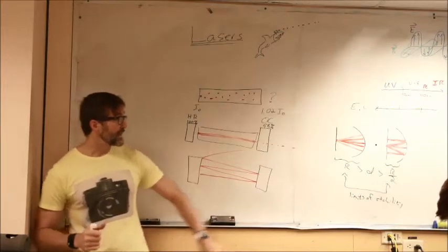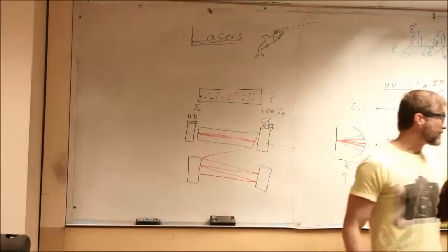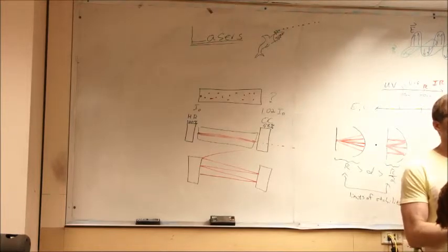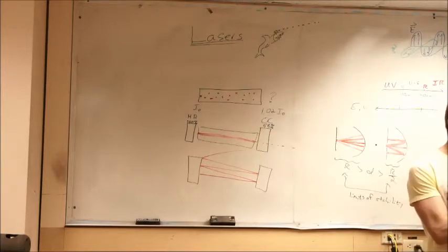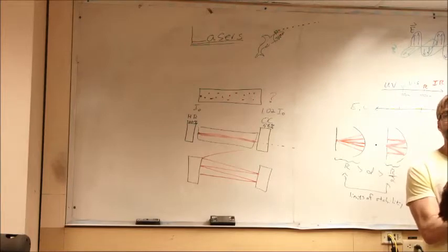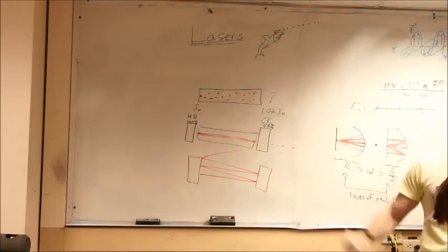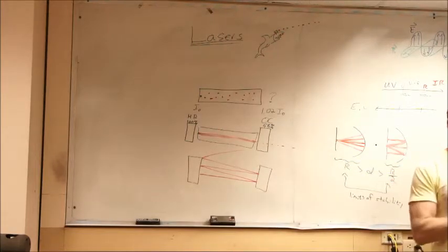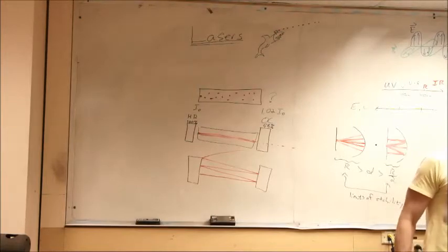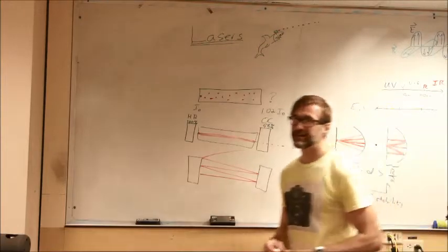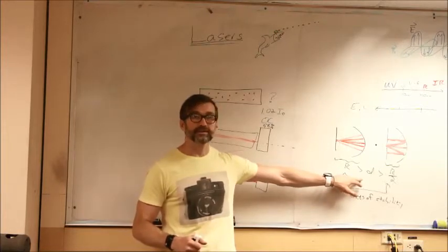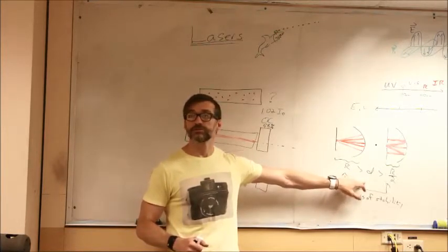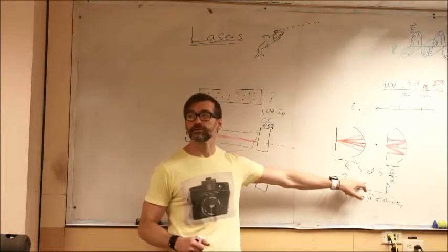So when you're putting your laser together, you already have the output coupler bonded to the back of the laser tube. You're not going to have to do anything there. What you're going to spend a large part of your day today doing is putting a mirror right there. Of course, you'll turn this on, but you'll put a mirror right there. You're putting the output coupler in front. The trick is if you put it in there and you get it in the right orientation, you'll get a laser. Of course, if it was as easy as it seemed, I wouldn't dedicate an entire day to it. All right. But one constraint is that you have to make sure your output coupler is placed at least somewhere in this range from the high reflector. Otherwise, you won't get a stable resonator.